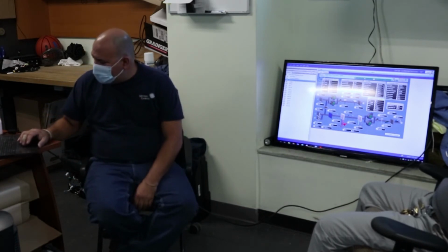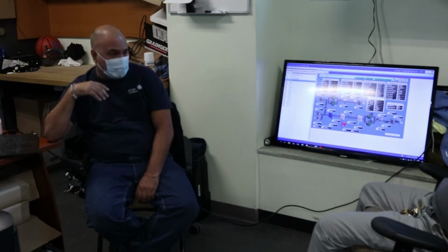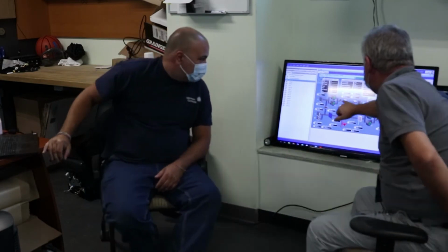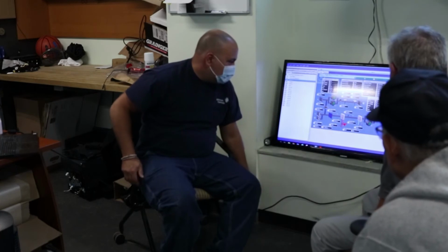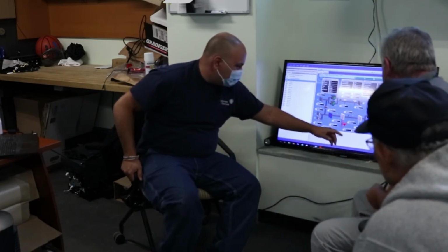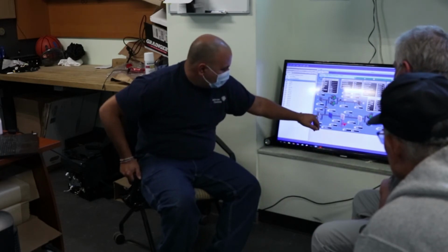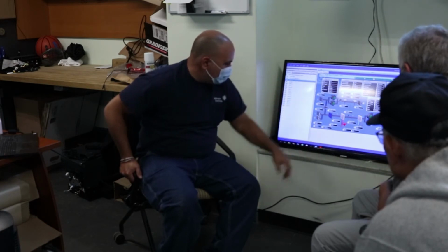Okay, well, we're on the air handlers. Any other questions with the air handlers? You guys are pulling in a lot of outside air on these air handlers. Well, you have an economizer. Plus, you have no heating, no cooling. The cooling's disabled. Your economizer is working, so that's why you've got outside air.